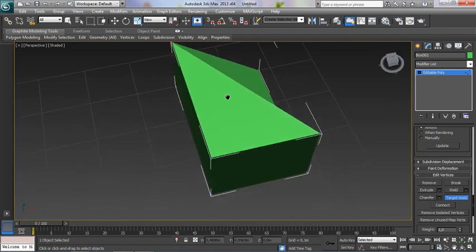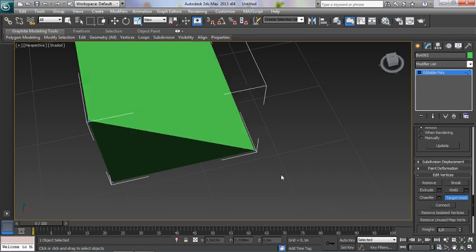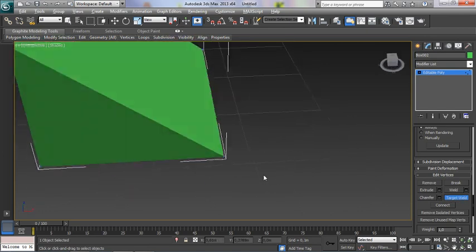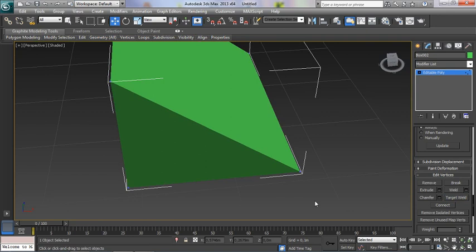I'm going to use this again. I'm going to make this vertex be welded here. See that this is still selected, so I can make this vertex go to be welded there. And that's a different way to weld.